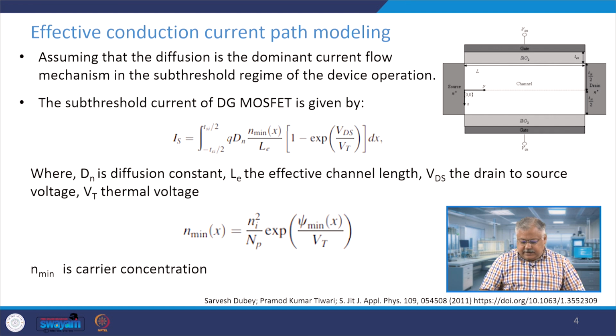So, on the right hand side, if you see, this is the double gate MOSFET, the device. This is the device which we are going to look into. Double gate, this is gate number 1 and this is gate number 2, and we can actually have these as a tied gate configuration, primarily meaning that the two gates are tied together. So, whatever potential you give to gate number 1 also appears in gate number 2, and therefore, the inversion layer is exactly formed in the same way as in the top gate as in the bottom gate.